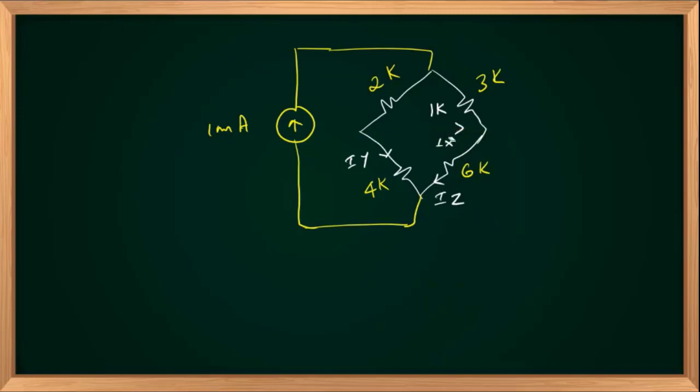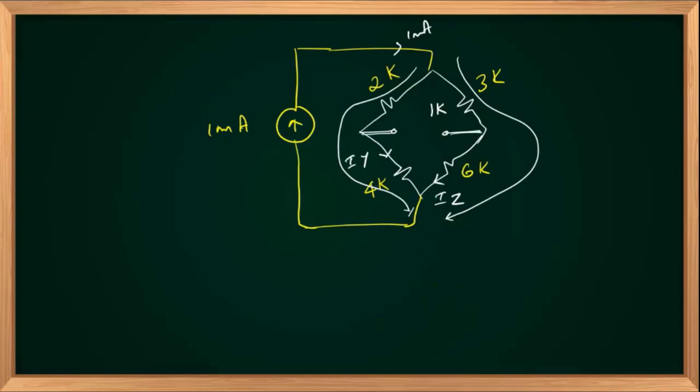So we will open it, right? Open it. So that branch is opened. We have 1 milliampere current here. And that current source observes two different branches. Right? So based on the current division rule, you can write this branch current in the open circuit condition. It is Iy. The other branch current is nothing but Iz when this branch is open.